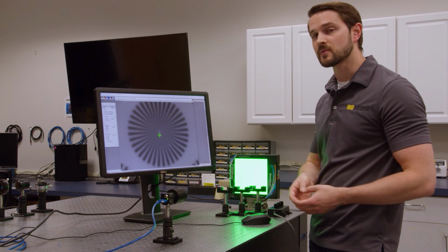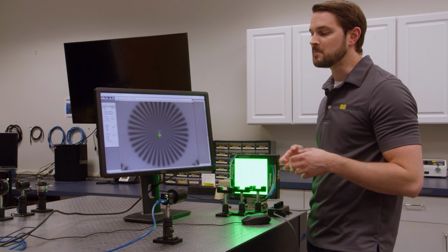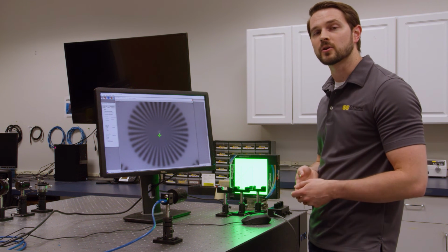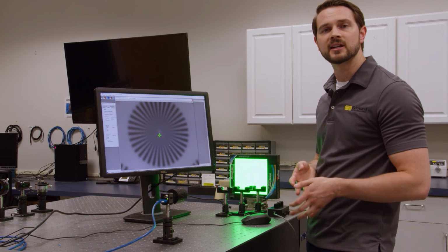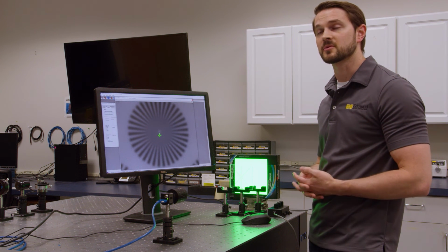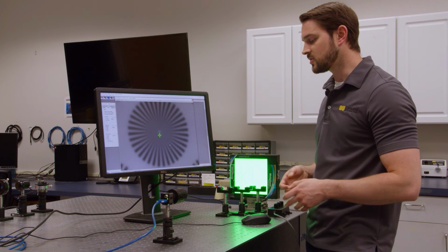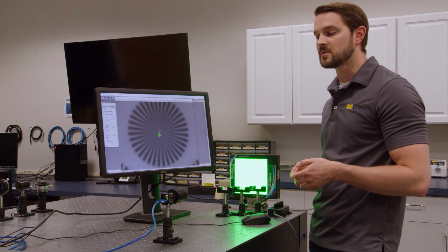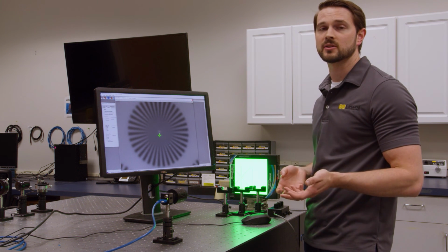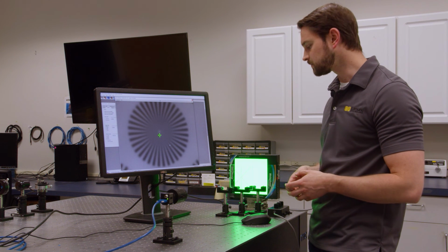And so even though theoretically you could achieve higher resolution with the lower wavelength there, most machine vision lenses aren't going to do well once you get below around 470 nanometers. Even when you get down into that violet 405, there are some lenses that perform relatively poorly. So usually in machine vision applications, I'll recommend to people to use blue or green. That also corresponds with, especially the green, with high quantum efficiency from the sensor side of things.